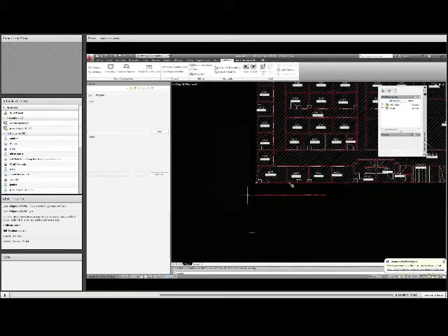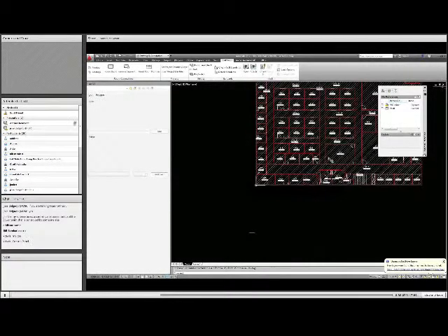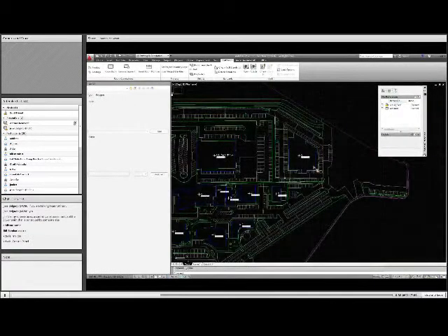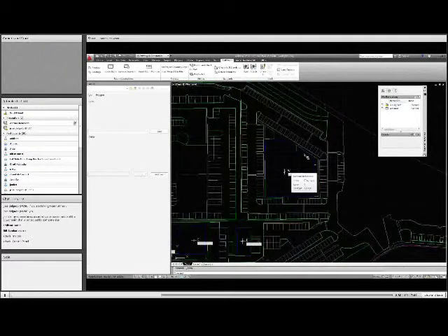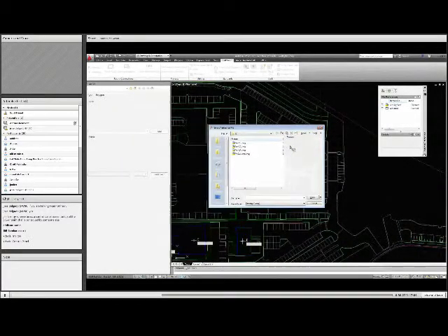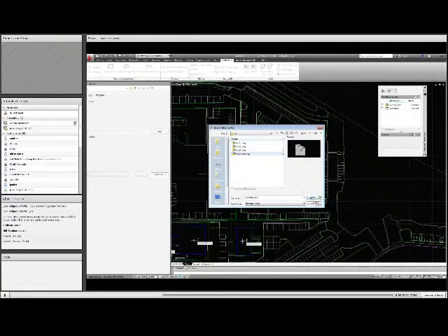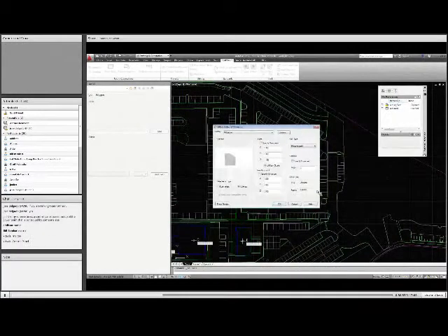Now, the fun part is there is a data frame rotation angle. So if you right-click up on your tools, there's a Data Frame Tools toolbar, and you can literally copy and paste the rotation angle that was calculated from CAD into the data frame, and that is a fairly perfectly rotated floor plan that matches the screen, not georeferenced. This is real nice when it comes to buildings that are rotated, like this 45-degree building here. Those can be really problematic to deal with.